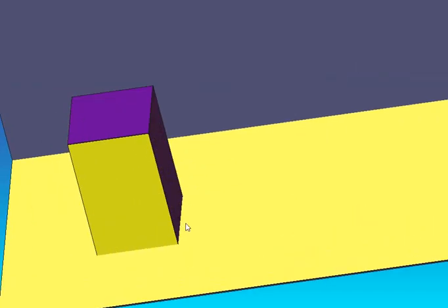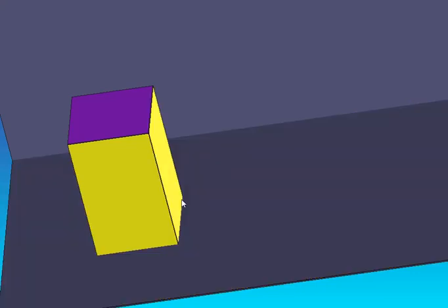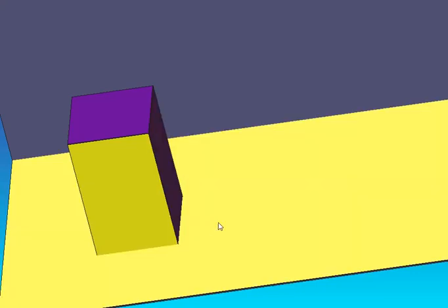When I tilt it, it is going to be resting on one of the edges. So I need to keep the edge on the right side. In case of planes, we kept the edges or corners on the left side. But in solids, we are going to keep the edge or corner on the right side when we tilt towards the right side.